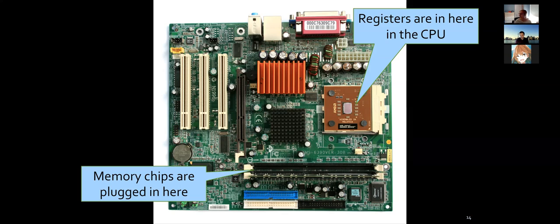There are two factors. First of all, SRAM is more expensive than DRAM. SRAM is a technology that I'm going to describe today that is used for both registers and caches, and DRAM is used for main memory. But to answer the question, why not have just tons of registers? They're very costly, they're very power hungry, and the more you have of them, the slower they become.